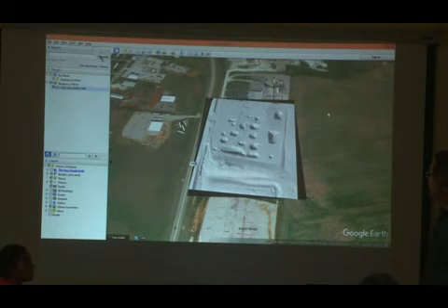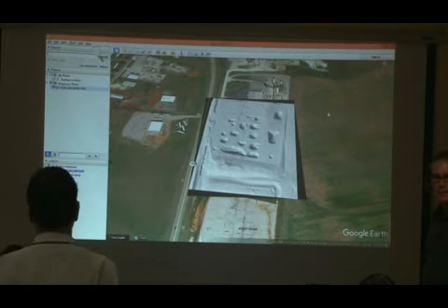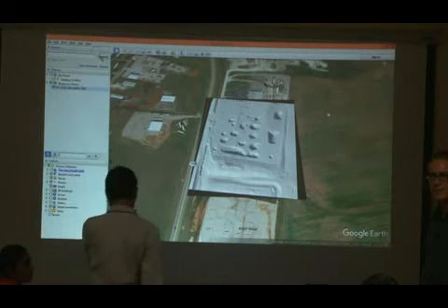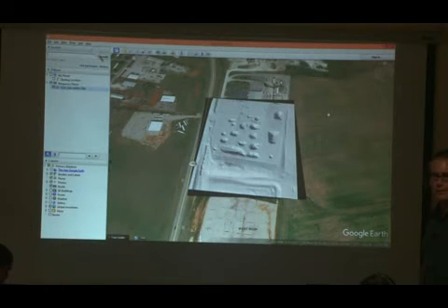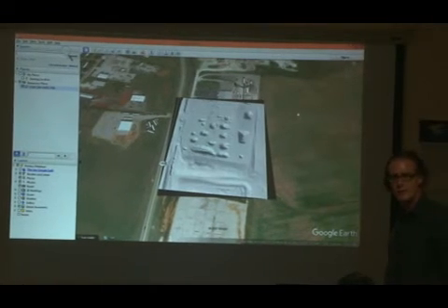I have very rudimentary support that allows you, for example, after you misclassify trees as buildings and you figure out what the green value is of the trees that you misclassified as buildings, you could, for example, remove the classification of buildings that have certain RGB ranges.